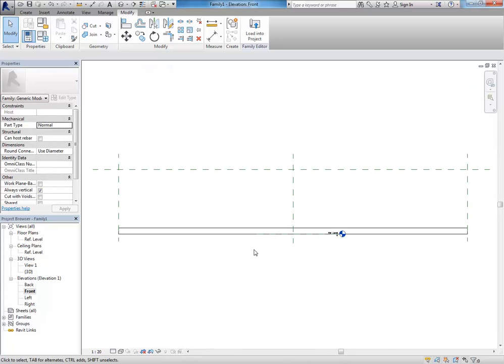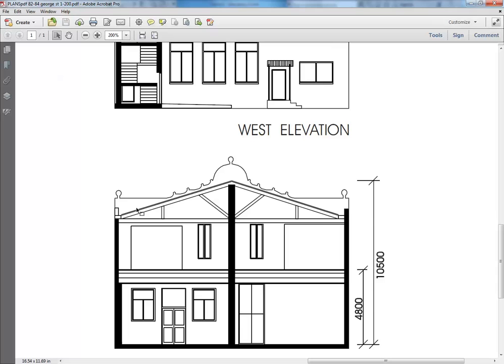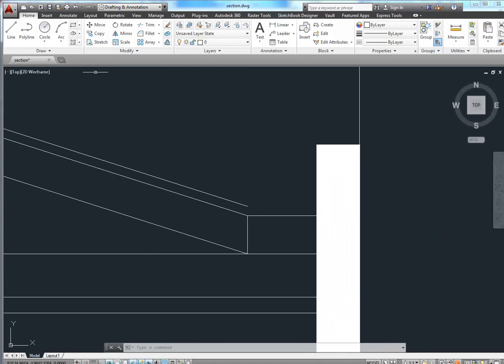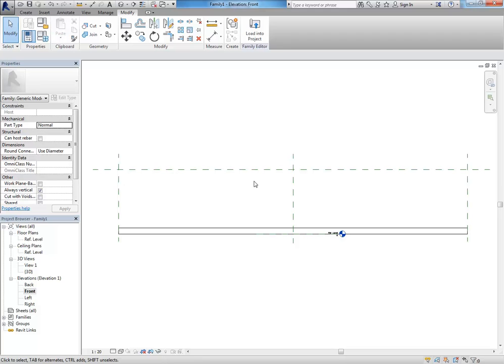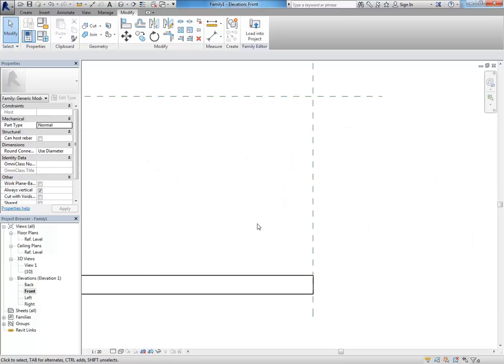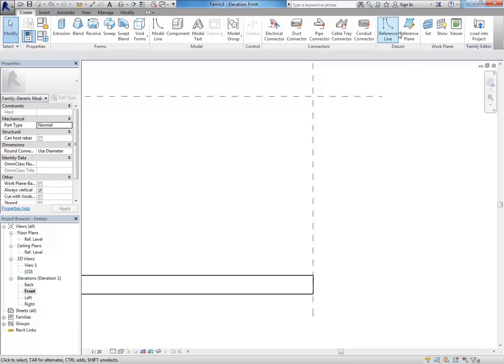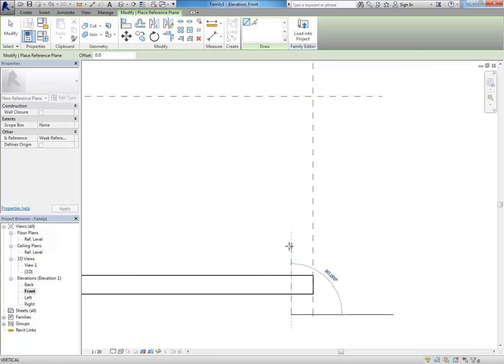Going back into that front view, then I can draw the other lines for the truss, and it's a fairly easy one to draw, so it's just another couple of extrusions that are going to give you most of it. So the rafter, that main member going at the angle there, is essentially projected off the gutter. So yeah, you definitely want to set that out next. And so we've got there again a distance from the end, so 400. And so again, it doesn't hurt to draw in a reference plane for that. So 400 from the end of the beam.